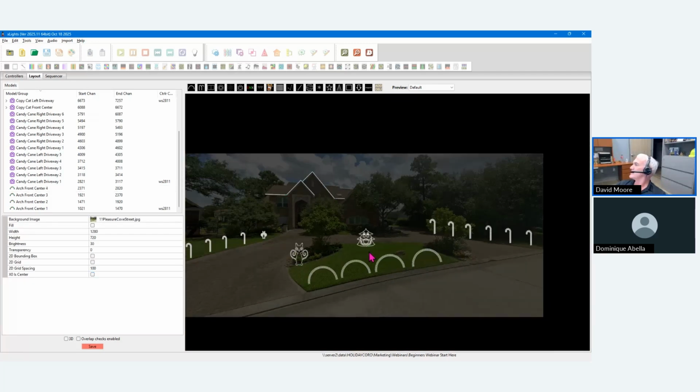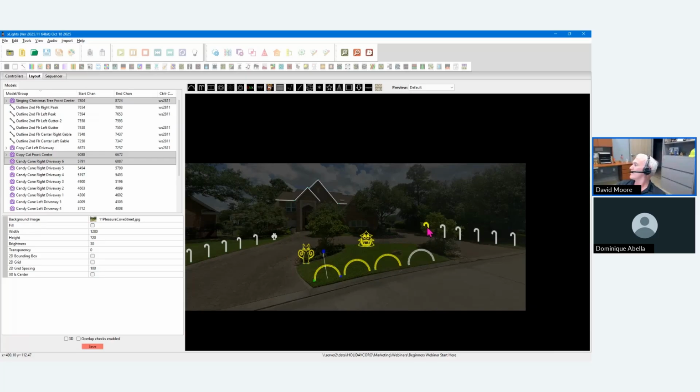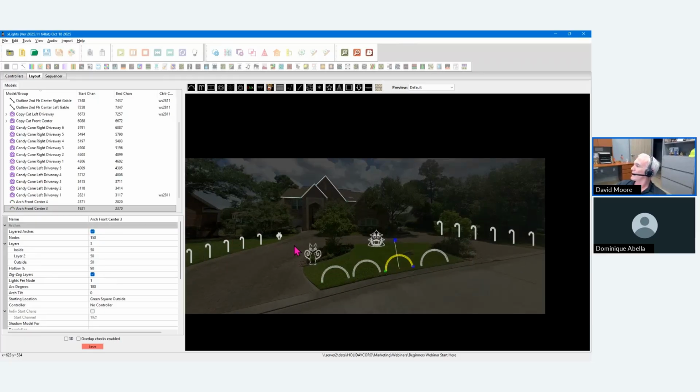So we're going to use a 16 output local SPI connections for these items, not that one over there. And then we're going to use long range going over here, and then I'm going to daisy chain off of this left side. So I'll get my cable across the driveway up and then into the house. And then this one, I'll go over to the right. So we're going to daisy chain 2 of these receivers and then one over to the right.